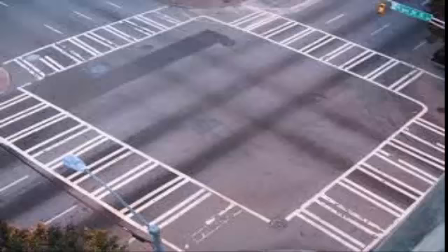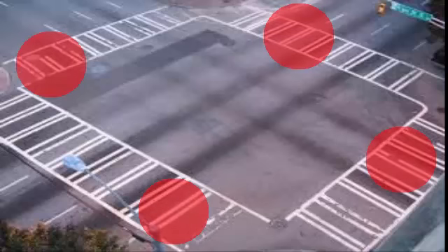When there are no vehicles at an intersection, the controller can be programmed for red rest operation, displaying the red indication to all approaches. The controller will provide an immediate green indication to the first phase where vehicle demand is sensed. After the demand is serviced, and assuming no other demand occurs, the intersection will return to red indications on all approaches. Red revert timing is used with red rest to ensure that unreasonably short red intervals do not occur.